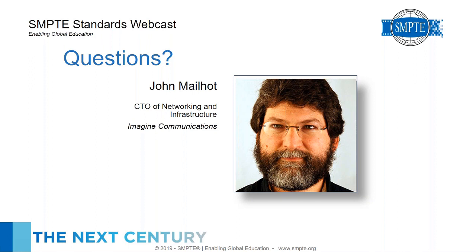Patrick asks, does AES67 mandate the use of 239.0.0.0/16? Boy, that sounds like a trick question. It may, and that may be a place where 2110 and this TR are more broad. In practice, I'd have to look it up, to be honest. I don't remember if that was restricted in AES67 or if it was a should. Sometimes in AES67, there are a lot of things where it says should.